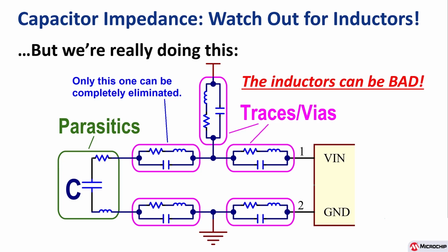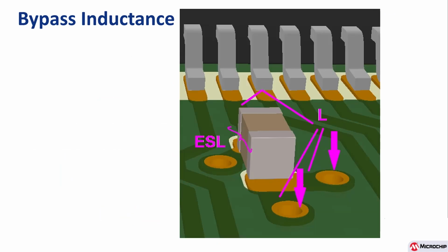So what we want to try to do is try to make our capacitors act like capacitors. By reducing these stray inductances, the resistance makes less importance to the total interference with the capacitor function. So let's look at this illustration of a device on a board and its bypass capacitor that's routed to its power pin. So the second from the left pin is the power pin.